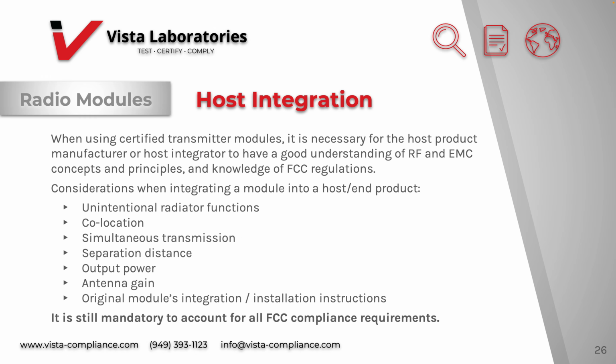Host integration. When using certified transmitter modules, it is necessary for a host product manufacturer or host integrator to have a good understanding of RF and EMC concepts and principles and knowledge of FCC regulations. Considerations when integrating a module into a host end product: unintentional radiator functions, co-locations, simultaneous transmissions, separation distance, output power, antenna gain, original modular integrations, installation instructions. It is still mandatory to account for all FCC compliance requirements.